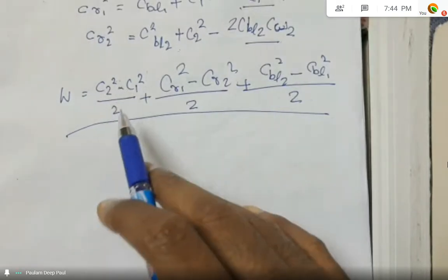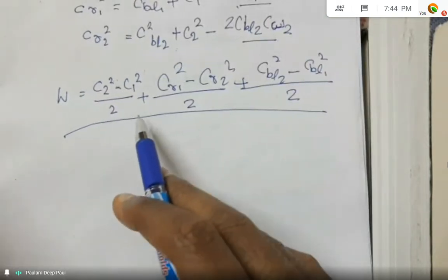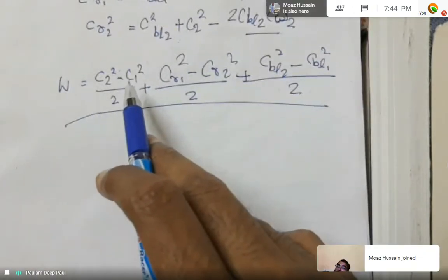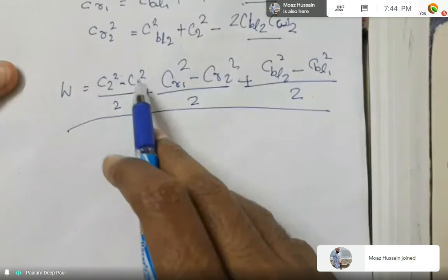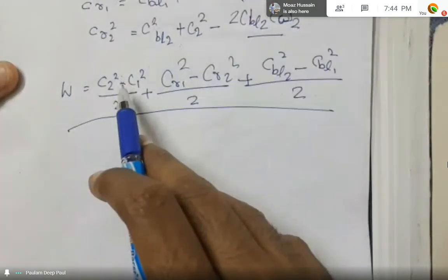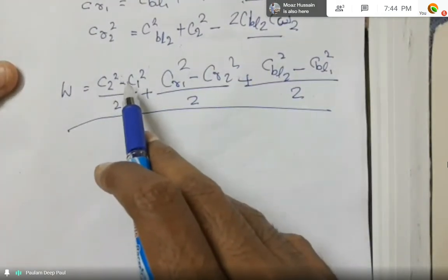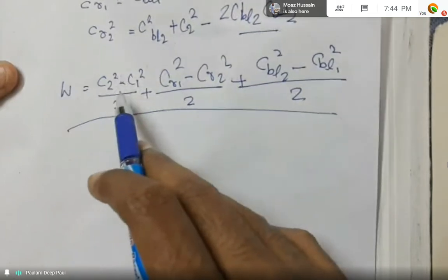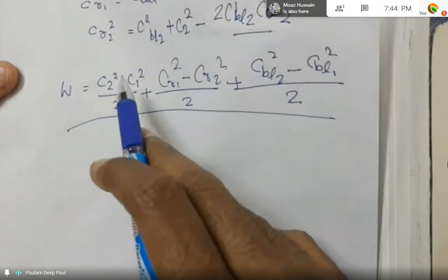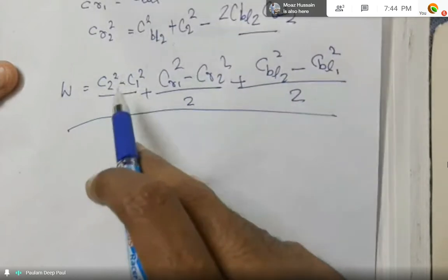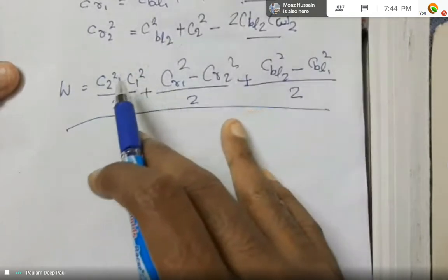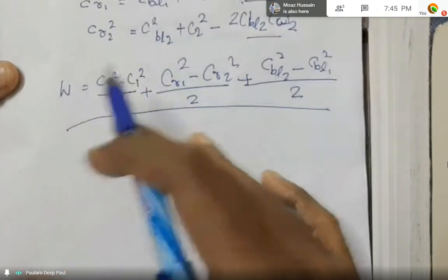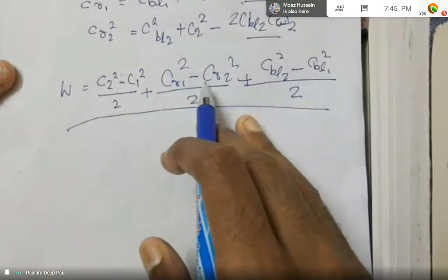As the air enters the impeller, this is the amount of kinetic energy that is increasing, and this much kinetic energy needs to be converted to pressure energy because we are dealing with compressors. So we need to increase the pressure, and this conversion comes in at the diffuser stage.